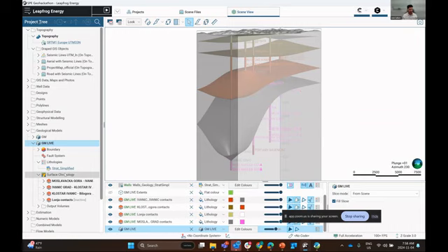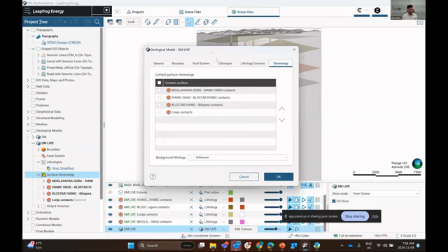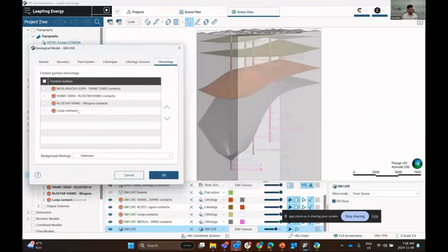So to start activating these surfaces and building volumes, we can double click the surface chronology, which is going to define the Younging direction or the cross-cutting relationships associated with each object. Objects or surfaces that are higher up on this list will take precedence over surfaces that are lower on this list in areas of overlap.